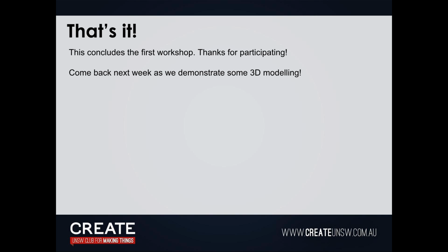Yep, there we go. Now you get all these different options. Still loading. You have to place the object. Yeah, I know. I've done this in industrial design. Pain in the ass. Right, so you can place your base view, right? You can choose your orientation. So that's front view. If you want isometric view, which is something like that. I'm not a huge fan of it, to be honest. If I do isometric, I do southwest isometric. It doesn't really matter too much.